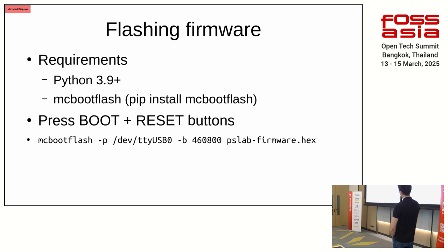If you have a PSLab in front of you, you can go ahead and hand these around. Anyone who wants to follow along here, just grab a PSLab. The PSLab has a button labeled boot and a button labeled reset. To enter bootloader, you press the boot button, and while you're pressing the boot button, you briefly press the reset button, and that's going to make the PSLab enter its bootloader mode. You will know that you were successful if the status LED starts blinking.